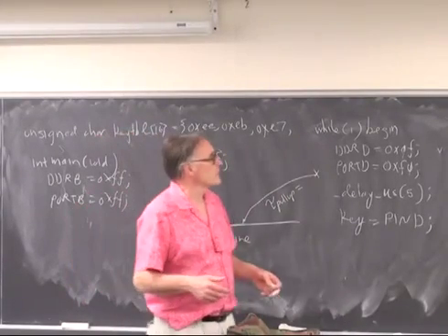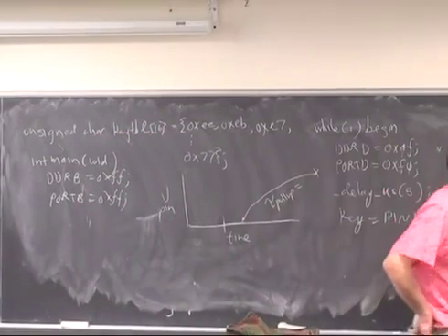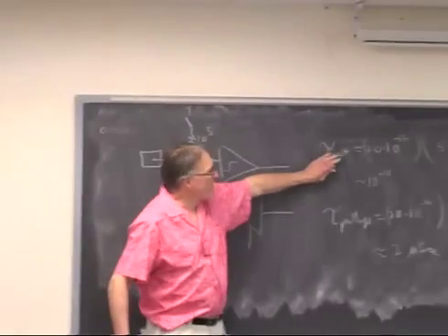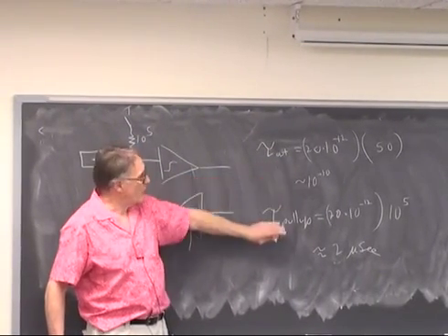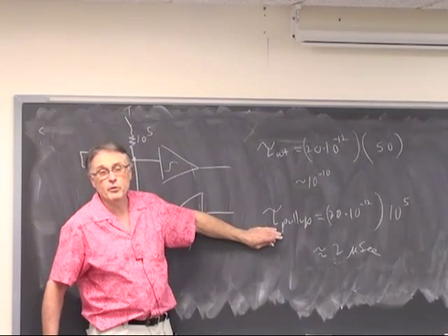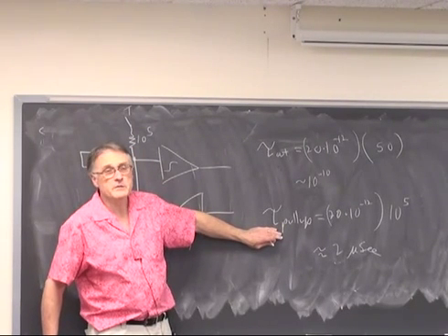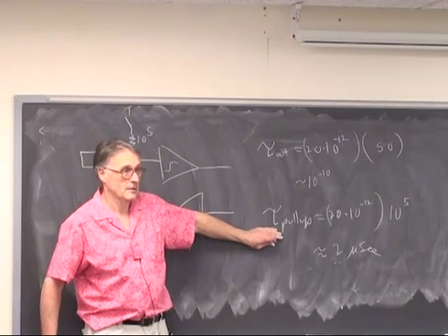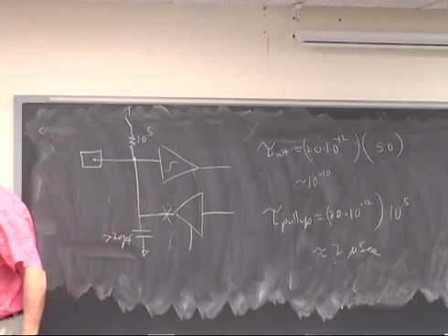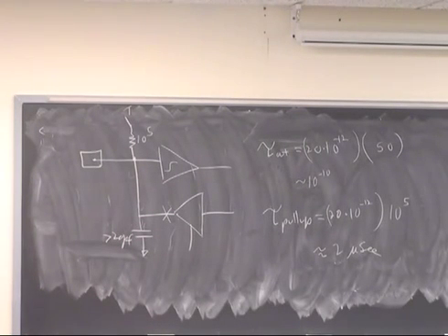So even though with output active, the time constants are trivial. With the output inactive, but the pull-up turned on, the time constants are on the order of 30 or 40 cycles. And so you have to delay for some amount of time.